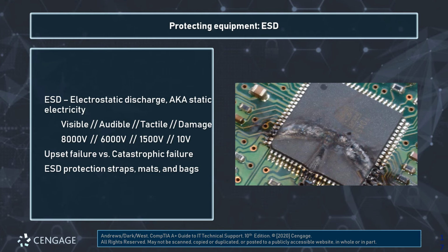So you can see just to the right of the center, where the three things have converged, the model number, and it's a Phillips chip, but right there you can see that there are 2 or 3 points at which the discharge occurred, going from 3 separate areas passing electricity into the chip. Enough so that it started to expand and ripple outwards and cause these char marks.